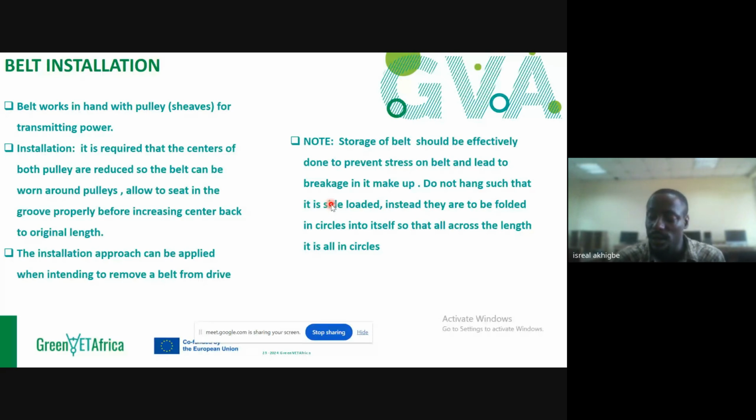So let's say this driver is supposed to fix on this point A, which is supposed to be mounted on a mounting foundation. And for some reason you didn't bolt it properly. Once it starts operating, the vibration, the force of centripetal and centrifugal will cause excess vibration, and as a result can tilt your driver away from the intended position.